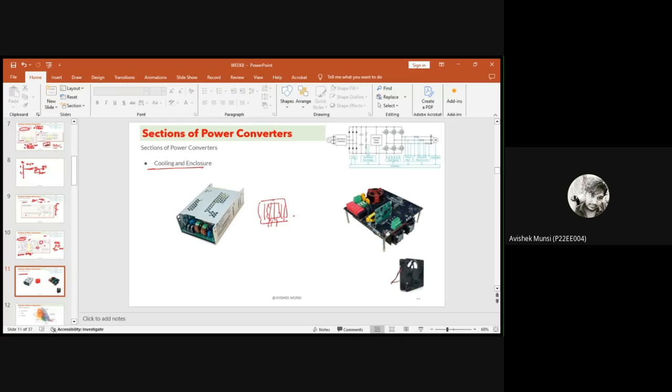I also discussed a way for SMD heatsink: we put some vias behind the MOSFET where you're placing it, for bypassing the heat from the copper plate. So in PCB design for SMD, we can use multiple vias around it to avoid the heat generation.